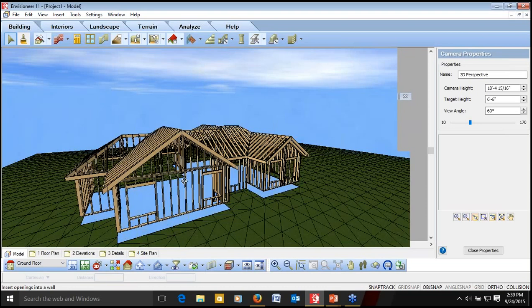So it's customizable, so it can follow your framing needs, so that when you're doing a bill of materials, it's not basing it on some type of formula, it's actually framing it, and it's framing it the way you prefer to frame it. You can tell it exactly how to lay out those studs in that wall, how to frame it in gable end situations. So when you get the material reports, you know that that's going to be accurate.